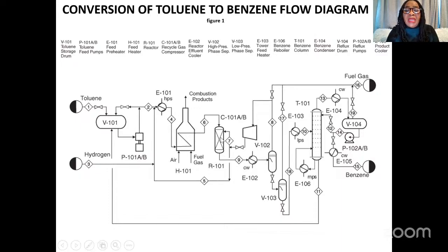This is the equipment. The R101 is this equipment. So input stream, of course, remember that the process stream is shown by the diamond icon. So we see input stream 6 here is the input stream to R101. You can see the direction of flow is coming into R101. Another input stream that is also coming into R101 is stream 7. You can see it here. So for R101, the input streams are 6 and 7.